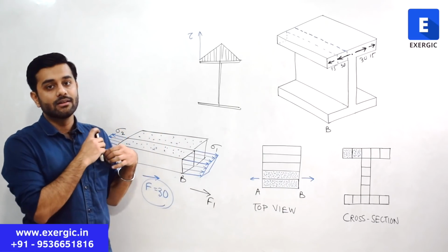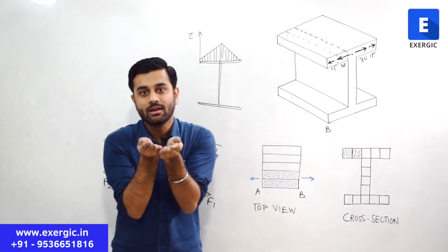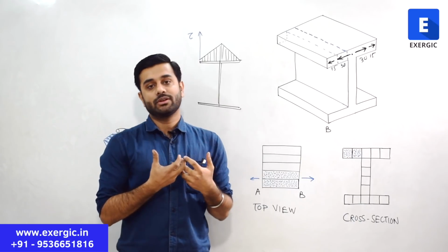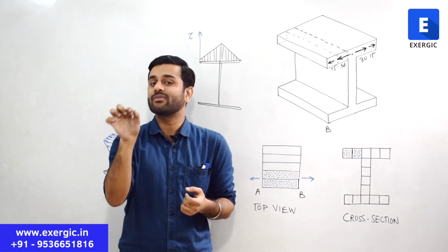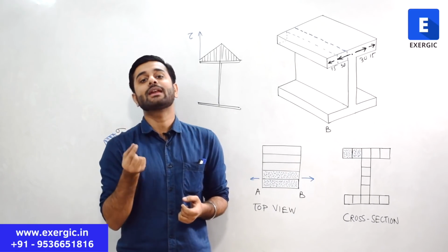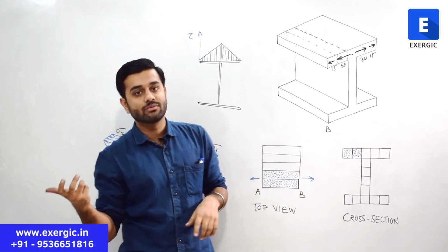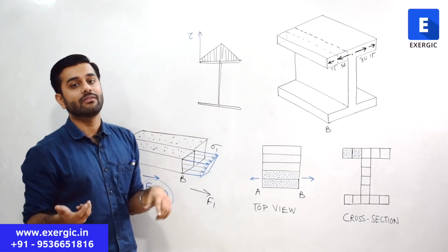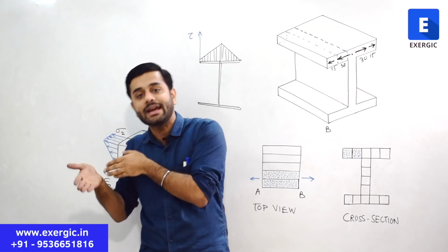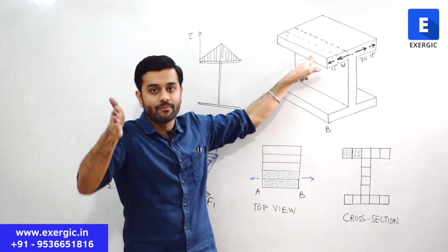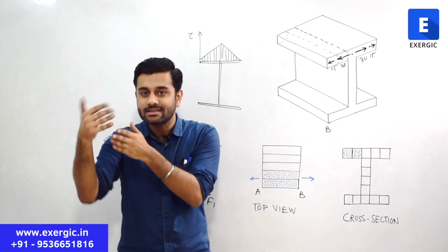Now, we considered a very appreciable part as a fiber. But if you want to do this analysis for an infinitesimally small fiber, like any small element, what will happen? The value of this force F, which you got as 15, will become 0. It will keep on decreasing as you move away. Consider this section is a very small, very thin section, almost at the right end. On that area, no shear force is acting, right? So there will be no force acting from the front side also.